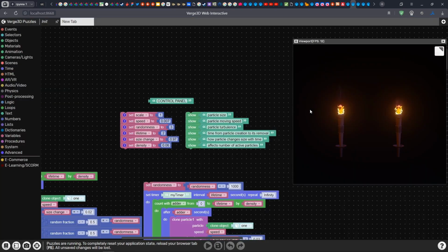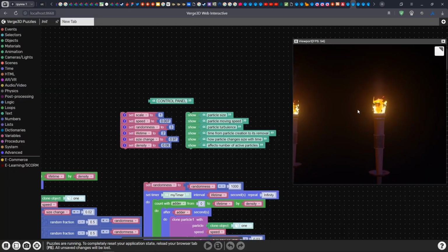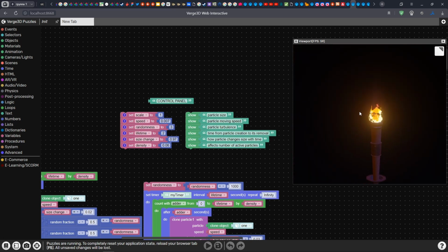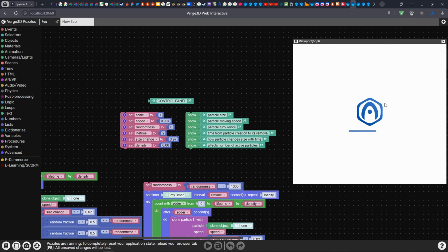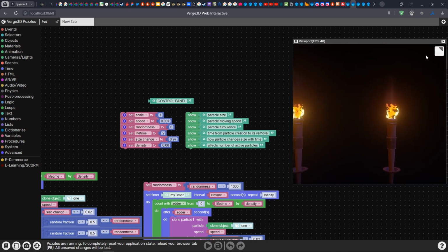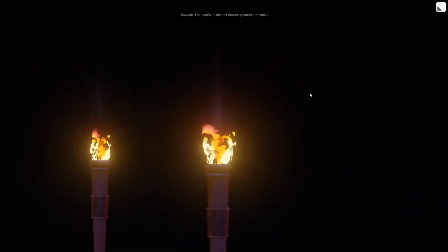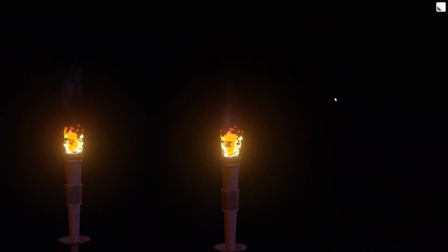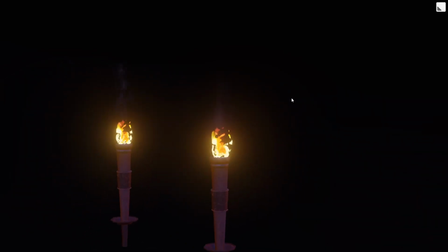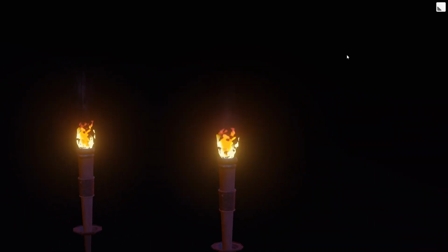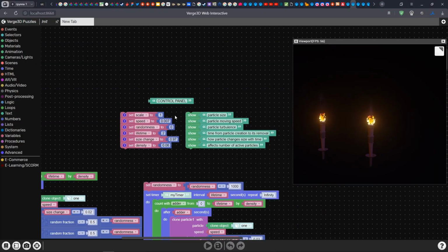So randomness is how chaotic the smoke behaves. Right now it rises almost straight up, but with some turbulence. If we set randomness to 0, the smoke will rise straight upwards, and it will be kind of noticeable. It will look more like a water flow than smoke. So maybe we don't want it, except maybe if it is a candle flame.